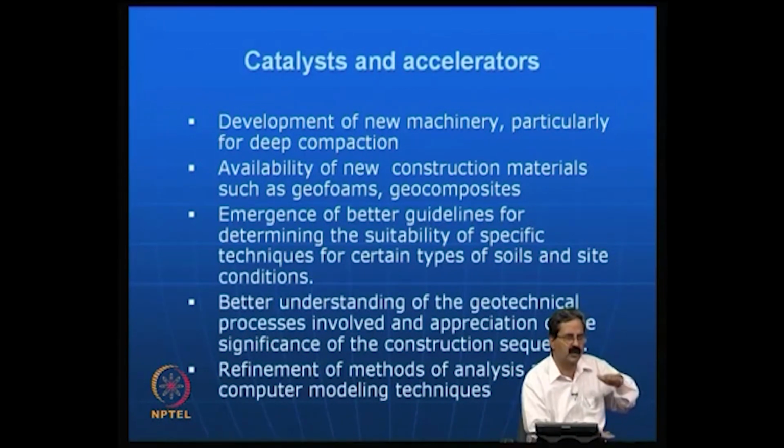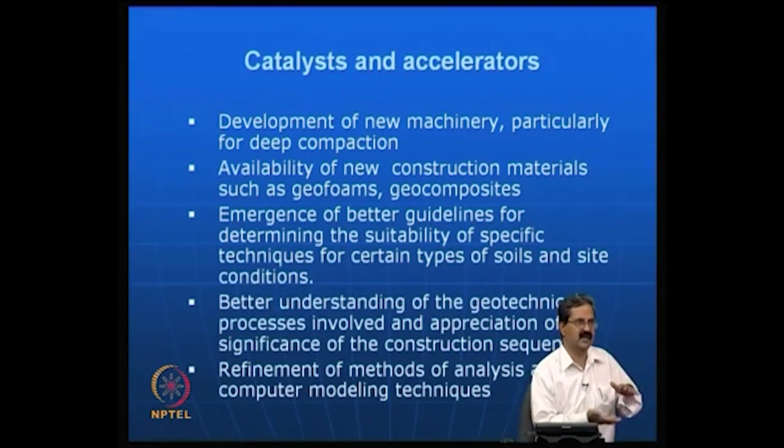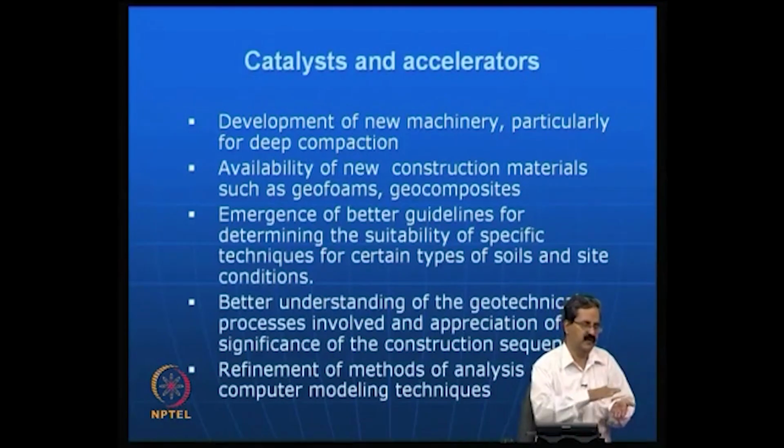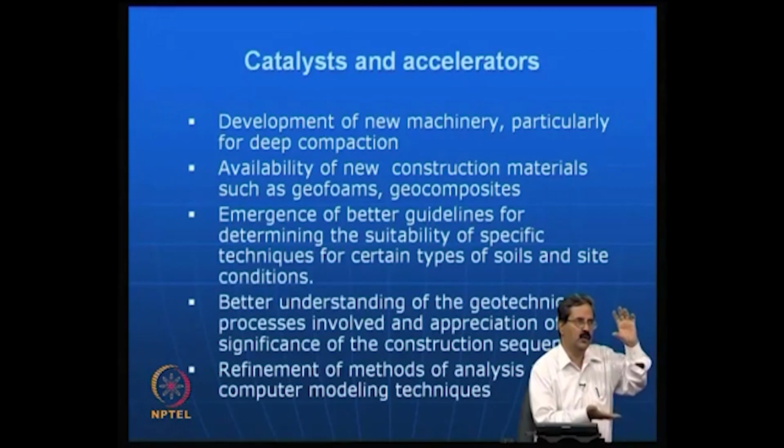What is the subgrade? Why are you constructing different layers? Essentially, we are constructing the road to see that the traffic load is taken care of, right. The existing load is some traffic loading, and you are trying to provide some material which can take care of the load, nothing else. All this concept of sublayers is just an older concept. Of course, the concept is important, the purpose there is to distribute the load gradually.